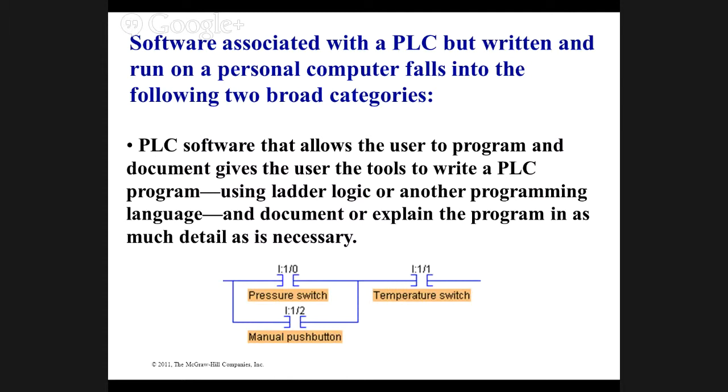Unless, of course, it's something real simple, you can get away with it. But this can be thousands of lines of code. And if all you have is numbers, how do you troubleshoot that? If all you have is I:1/10 50 times in a program, you have no idea what that is, right? So how do you troubleshoot it? You don't. You have to know what that means, and that's where we have descriptions.